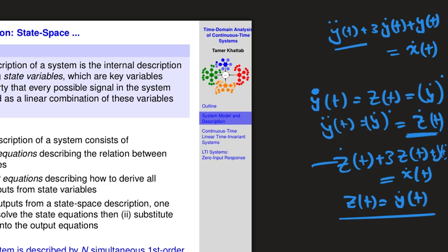Yes? The state space equations are always first order. But the output can be any order. Yes. And the order in input-output depends on the actual order of the system, if you did the derivation correctly. And in the state space, the number of state equations, not input-output equations, the state equations. You have two sets of equations, right? The state equations and the output equations. The number of output equations depends on the number of outputs. That's a different story. But each one of the state equations is first order, and the total number is equal to the order of the system.